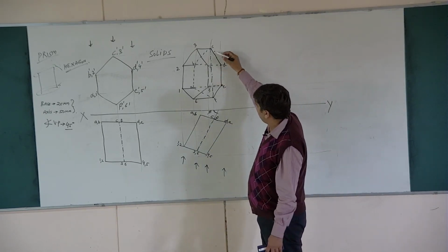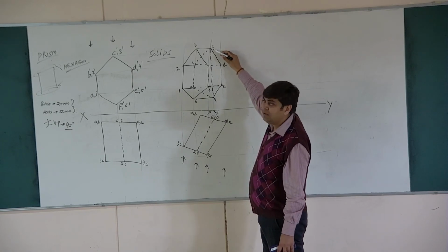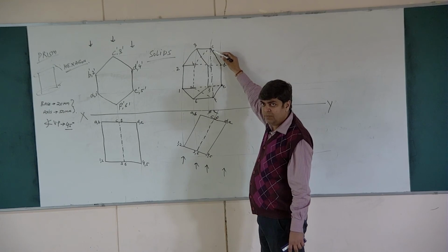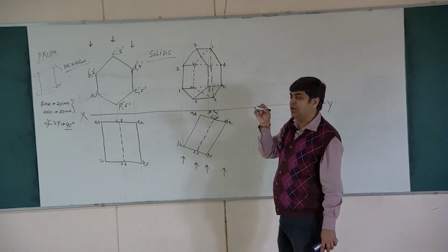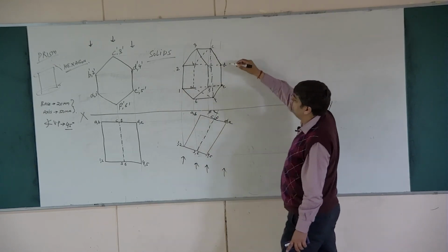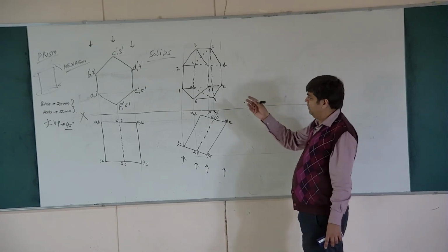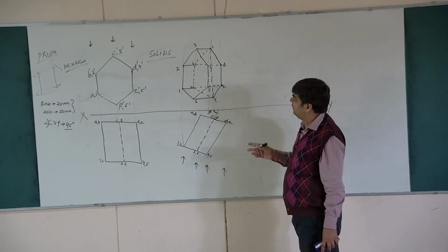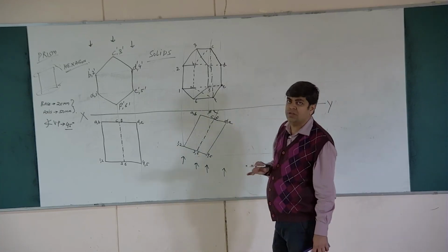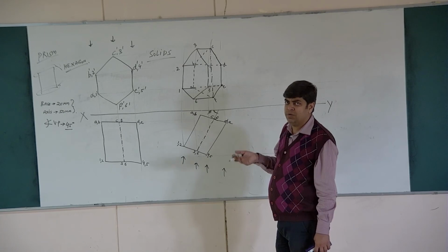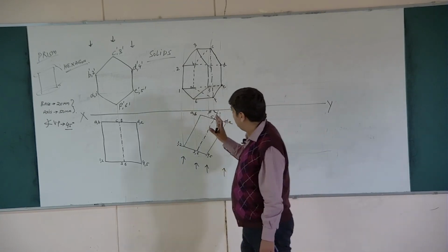Another important point, if the point is, as per the logic, hidden, but it is the outer boundary or the outer periphery, you have to close the solid, so it will be continuous. So you can practice this question and if required you can discuss with me. Similarly, you can try similar options in case of your pentagonal prism, square prism, triangular prism, and so on. So I am stopping this video. Thank you.